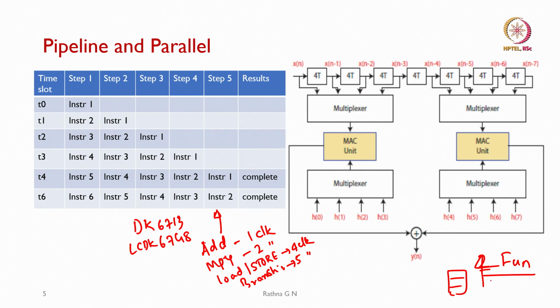So, if I operate them in parallel, 8 functions I can operate in parallel and each is 32 bit. So, we have a data width of 256 bits to get the complete instruction in one clock cycle. So, we said that when we use the two sides, we can do them in parallel.